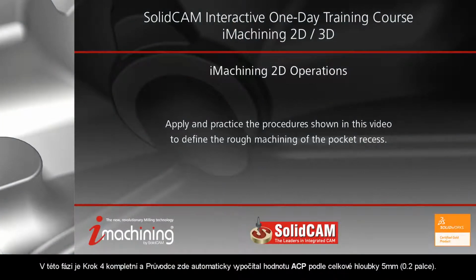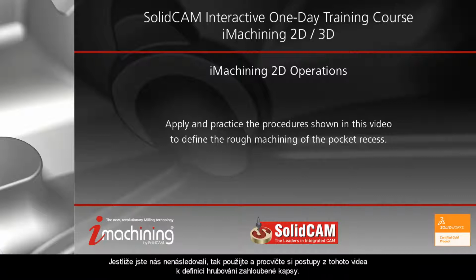At this stage, Step 4 is complete and the wizard automatically calculated the ACP value based on a 5 mm total depth. If you have not followed along, apply and practice the procedures shown in this video to define the rough machining of the pocket recess.